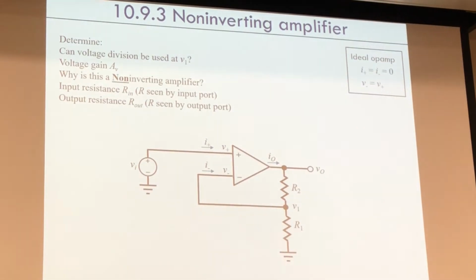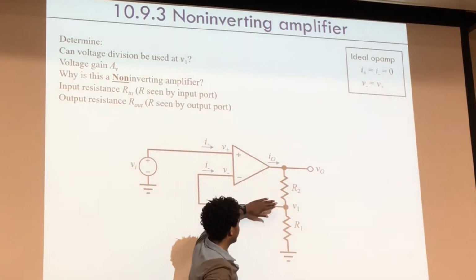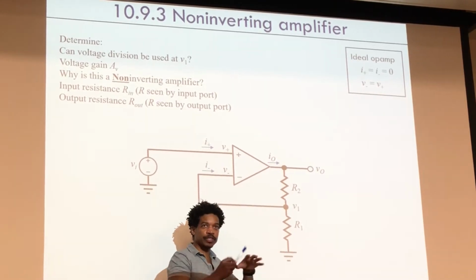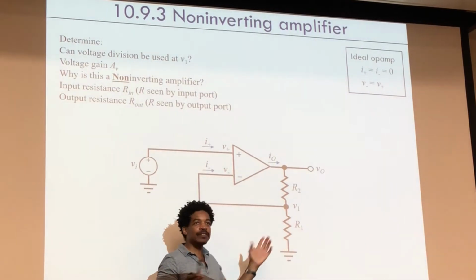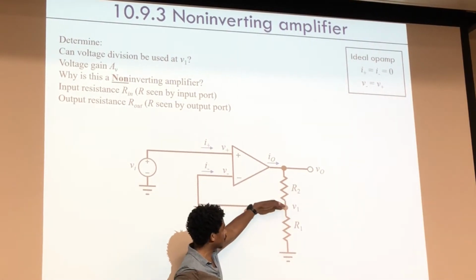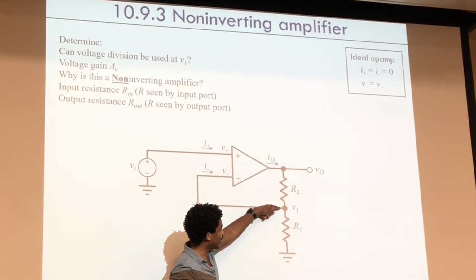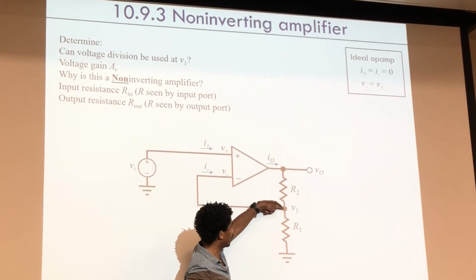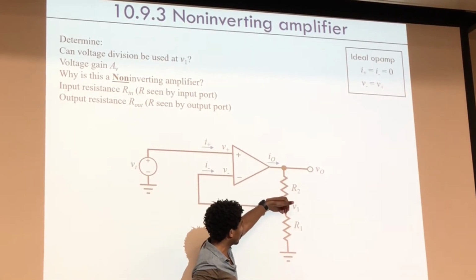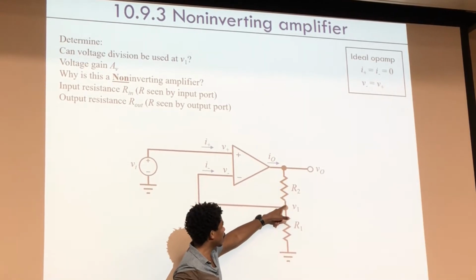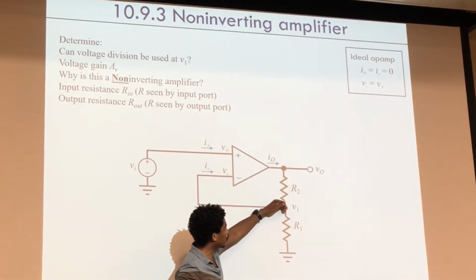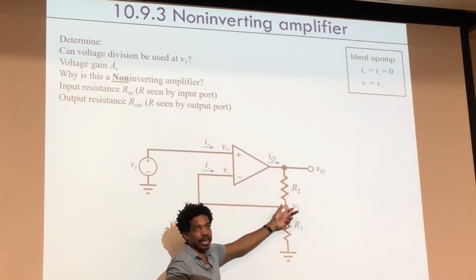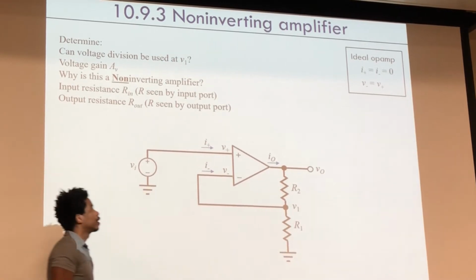Let me ask you this. If you didn't have this thing connected to it, and you just had a little test probe that didn't really disturb your system very much, and you looked for voltage, that's fine. But having something connected right here is a problem, because the voltage that I get through here depends on all this current going straight through and continuing that way. If some of that current goes here, I get a lower amount of current going through there. That's going to change my value of voltage. It's not going to be an accurate representation of voltage.